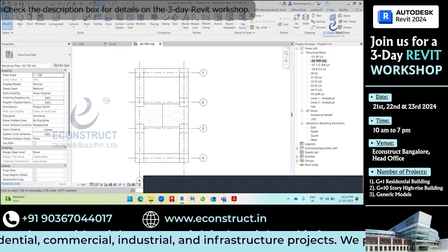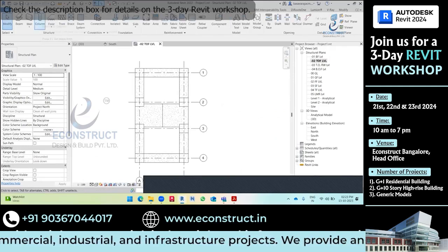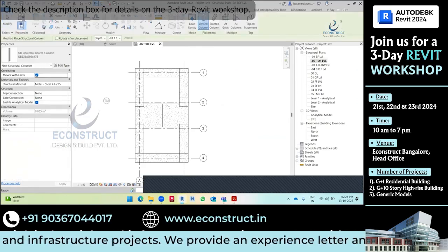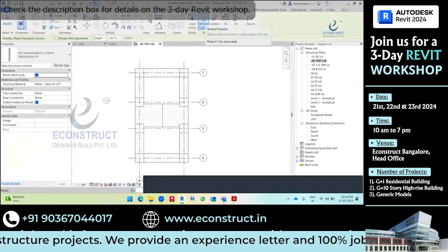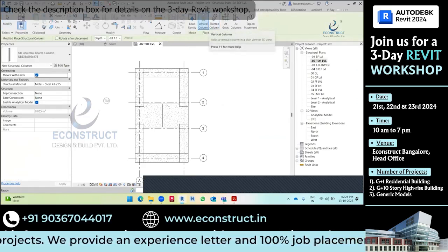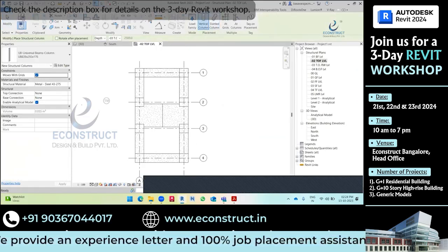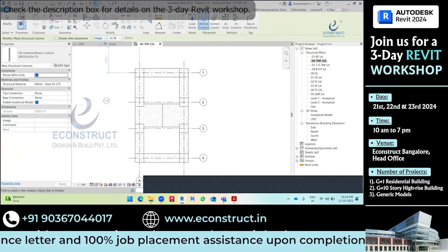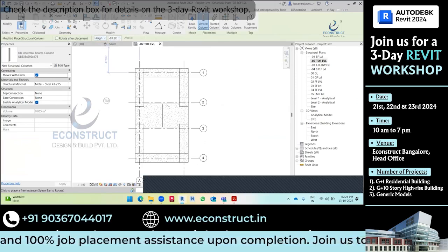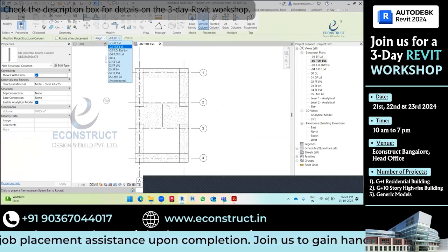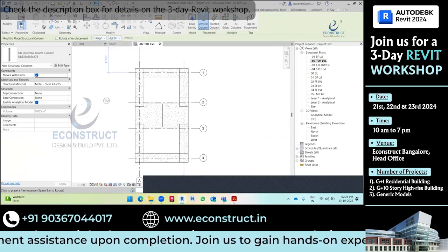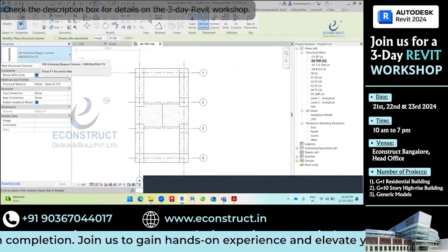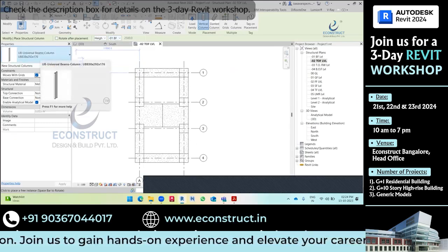To create the columns, go to the structure tab. In that, the column option is there. Just select the column option and make sure that it is a vertical column, not a slanted column. This should be a vertical column. And in the options bar, instead of depth, select the height. Select the height and give the constraint, like from top of the footing to basement floor level. Give the constraint and type. Now you need to select the type. Okay, it is a concrete column, RCC column.